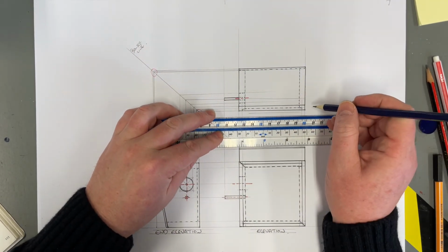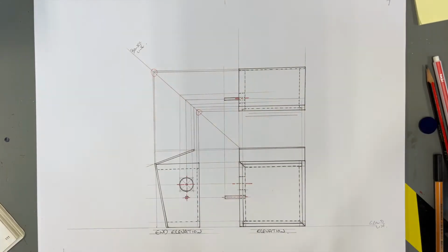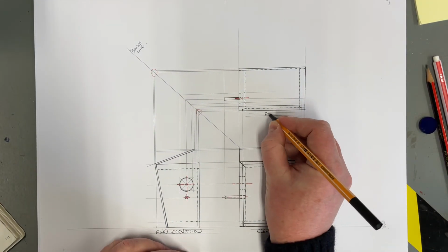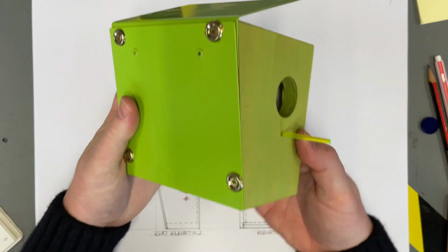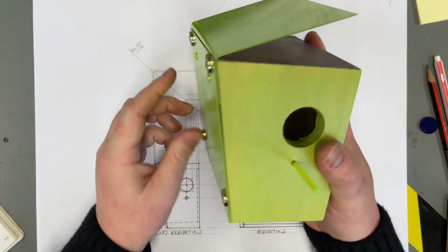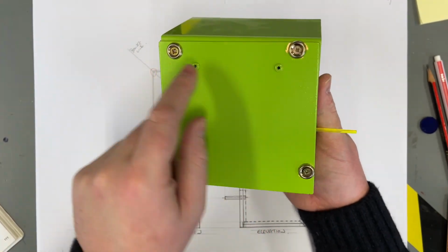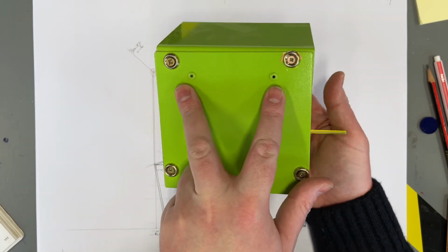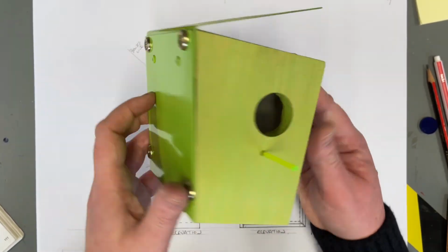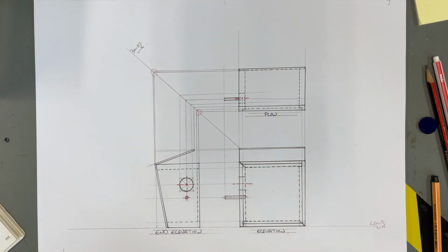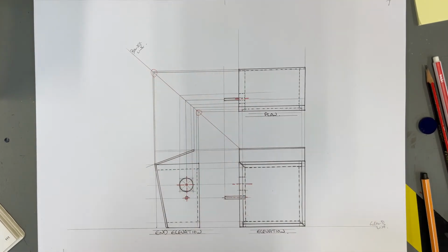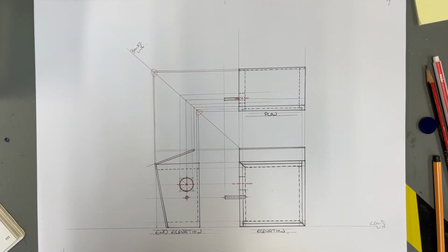Okay. Now, the only other thing that I could add into that, let's just do the view title before we forget. So plan, again, leave a little gap, 2 construction lines, and then the view title. And the only other thing that we could add in there is perhaps the joining technique that we've used, screw cups and self-tapping wood screws here, and we've got little pop rivets there as well, but these things I've still got to show you in the workshop, so I think we'll leave those off for today. As long as we've got an understanding of the layout of the orthographic drawing and then the dimensions, then that would be good enough. Right, so we're going to add in, to begin with, just the 3 overall dimensions.